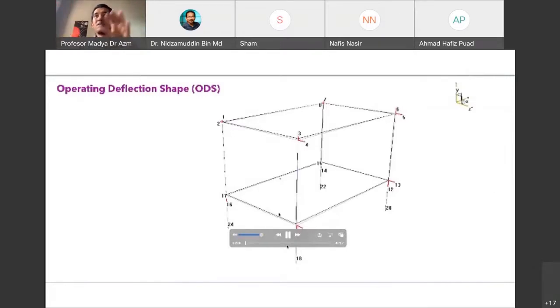The motion is not in opposite directions. The motor is rocking like this, but the base is fixed. If we suspect structural looseness, the base, from this side to that side, will be somewhere out of phase.